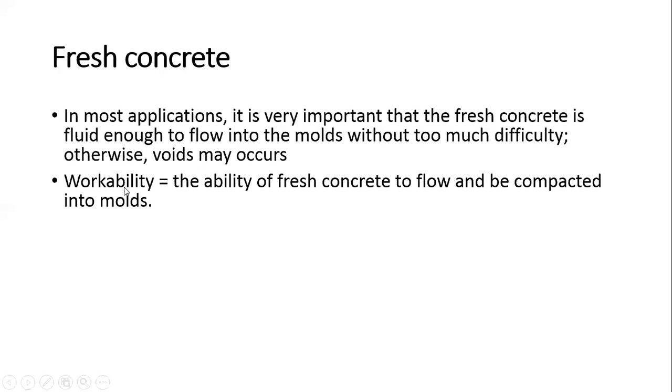So what is the meaning of workability here? Workability is the ability of fresh concrete to flow into the molds and be compacted easily. So basically this workability is comprised of two parts. One is the ability of the concrete to flow into the molds, and the other is that it is easily compacted.